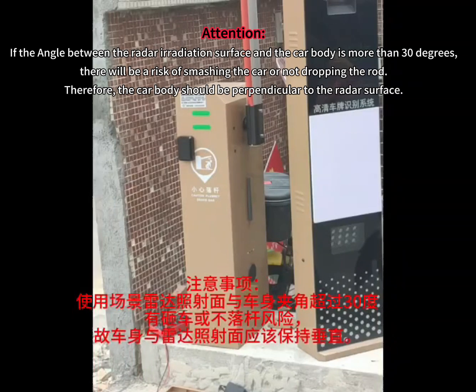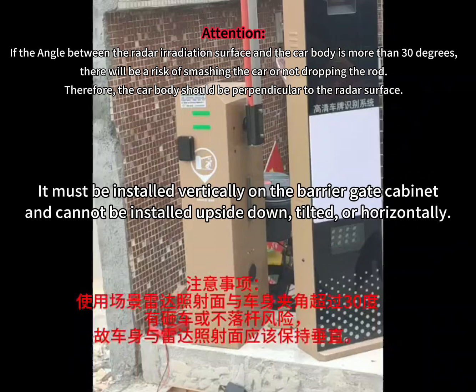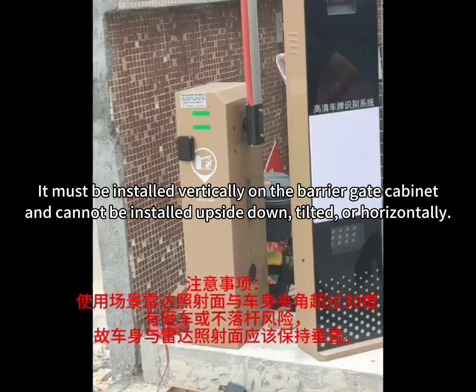Note, if the angle between the radar irradiation surface and the car body is more than 30 degrees, there will be a risk of smashing the car or not dropping the rod. Therefore, the car body should be perpendicular to the radar surface. It must be installed vertically on the barrier gate cabinet, and cannot be installed upside down, tilted, or horizontally.